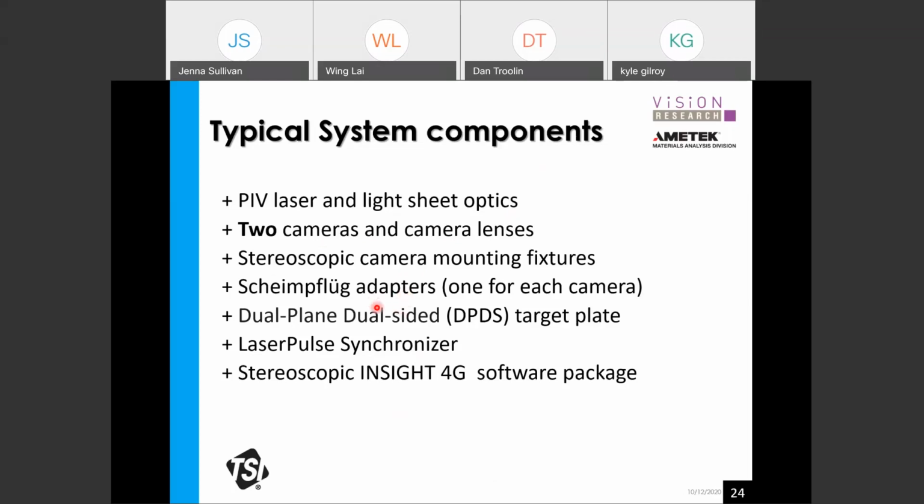In order to do the calibrations, we need to have a calibration target. Essentially it is to establish the relationship of the particle image from a target to the particle image on the cameras, so that we know what the distortions are going to be affecting the particle displacements.